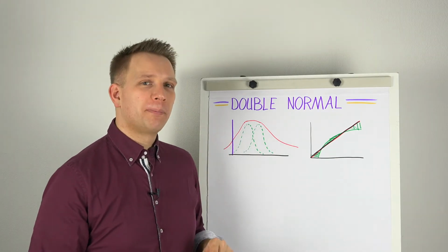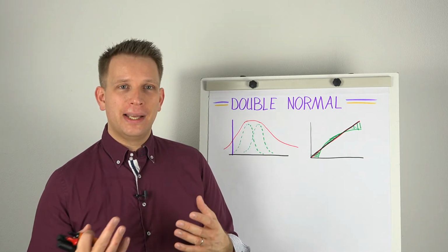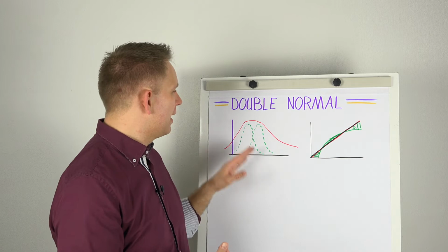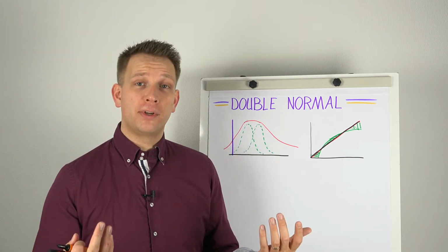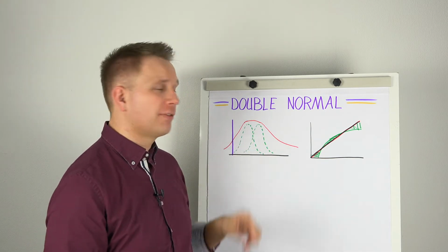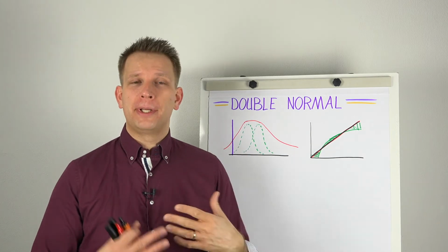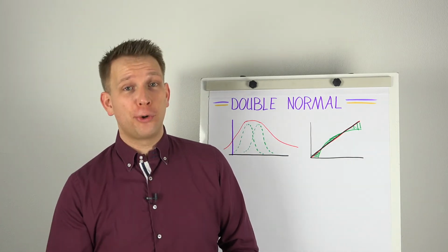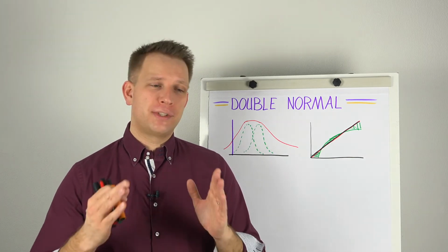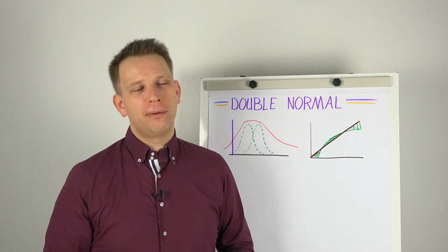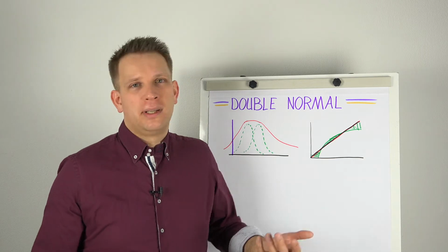On the solving part, we again go back to our friends, the t-test and also the difference of means. And there what you need is a lot of samples of both sides of the nozzles so that you can actually make these distributions. So go for 50 samples at least of either side. I mean, we are doing, again, standard deviation normality type of calculations. 30 is the bare minimum, but better is 50 or a bit more. More than 100, not really needed, unless you have really nice automatic data collection, so why go for it?